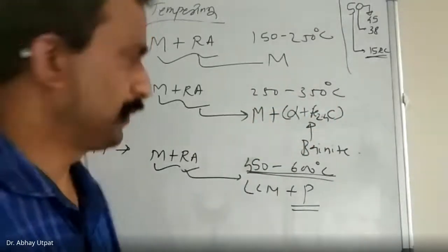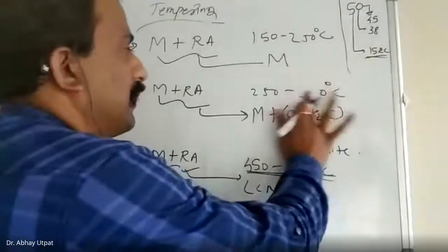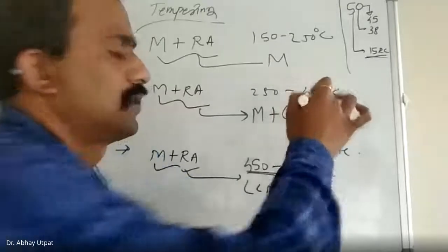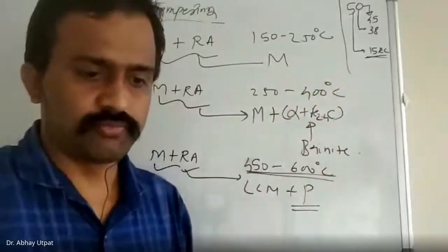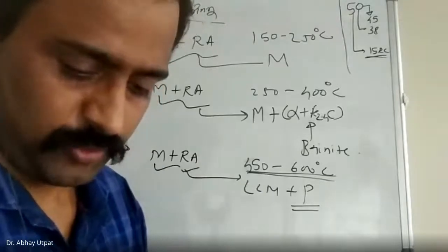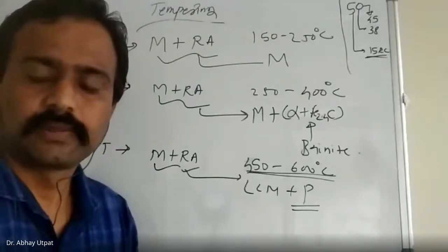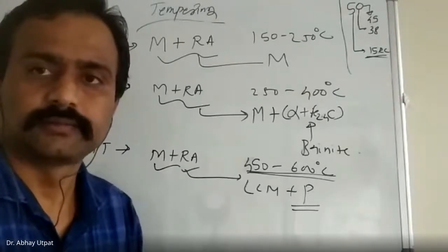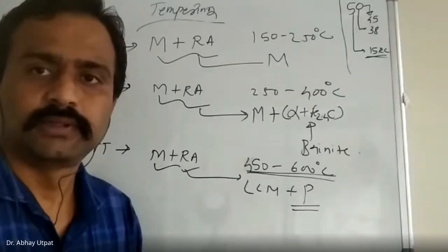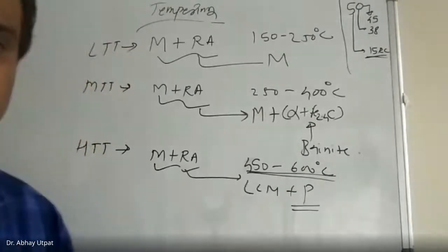You can say 250 to 400 also. 250 to 400 degrees Celsius, soaked there for sufficient time, and cooling slowly in the air.